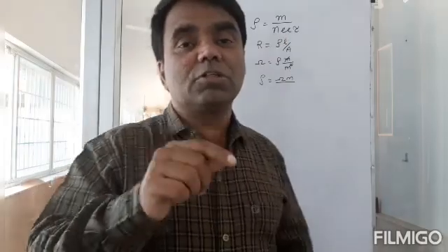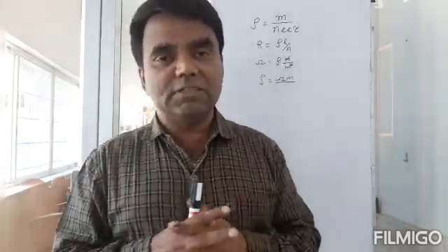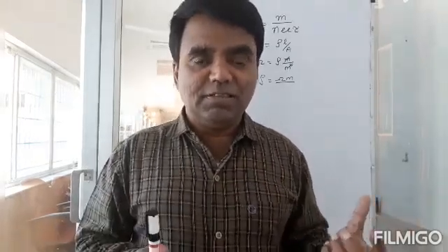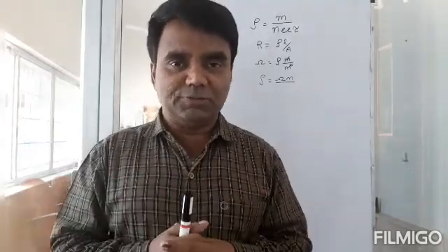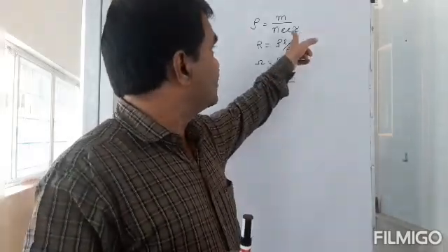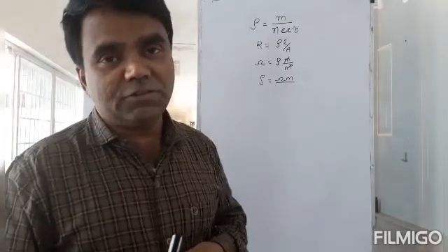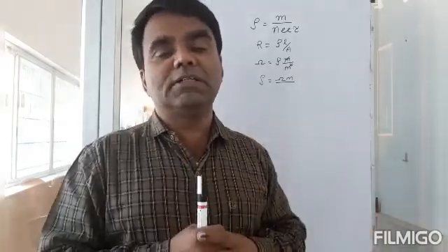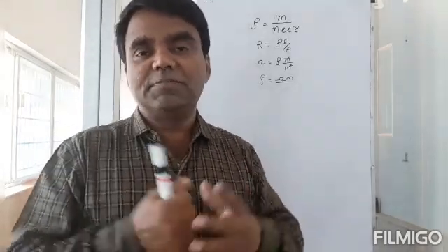So whenever we talk of rho, we'll talk of rho at a particular temperature, or you will assume rho to remain constant over a range of temperature also. Okay, so this is what we would assume. You need to understand that rho is not constant for a material. Rho can change because tau can change. The relaxation time can change because of temperature. As temperature increases, electrons move faster, thereby reducing the relaxation time. If tau reduces, then rho increases. Okay? And you have a table in your textbook that gives you the rho value for different elements, for silver and copper and gold and all that. Okay? It's given. So you can go through that and figure out for yourself what the rho value is for different materials. Okay, it's there in your textbook.